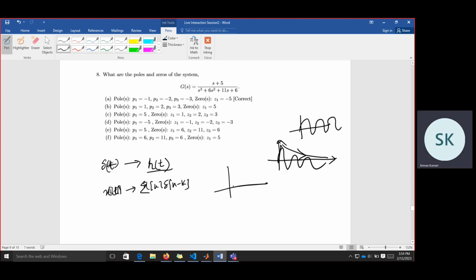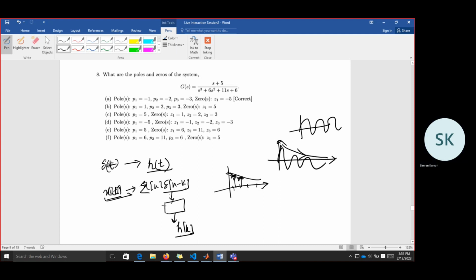Summation. So at every time instant there is an impulse, and this impulse is weighted with the value of the signal x(t) at each time step. So this is one of the things: every signal can be expressed as a weighted sum of this unit impulse. Now, if we know the response of the system to this unit impulse, which is h(t), then we can find out the response of the system to any given signal, because that signal can be represented as the weighted sum of this one.